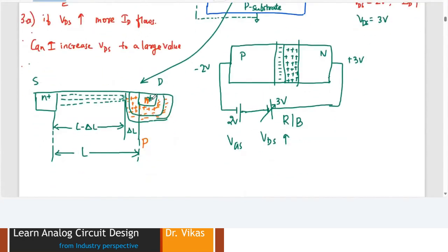But right now, nearer to the drain, there is an accumulation of a lot of electrons because of an inbuilt PN junction, and these electrons will be suddenly attracted towards the drain, and as a result, sudden and quick current flows at one particular voltage during which this happens.